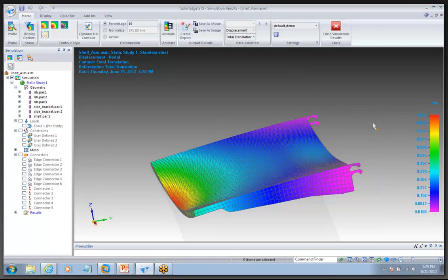So this brings me to a good point here. Because our stress is so low and our displacement is so low, remember our requirements were that it had to be less than 6 and it's under a millimeter, and our stress is really far under our yield. That's my new engineering term, really far. So what I want to bring up here is that a lot of people out there are making stuff now that they've been making for years, and they're like, well, it works, it's great. Well, that's great, but you could be saving a lot of money because you've over-designed it and you don't even know it. When you under-design it, you know it because it fails. When you over-design it, you don't know.